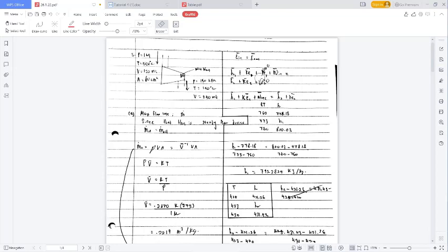Because there is no elevation change in the system, we can neglect the potential energy. Usually we neglect the kinetic energy for a turbine because the difference in kinetic energy doesn't contribute much to the energy summation, so some people will neglect it, but for this equation I have already included it, so we will deal with an energy equation that has kinetic energy for the turbine.